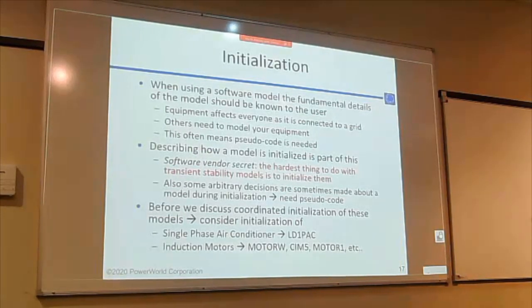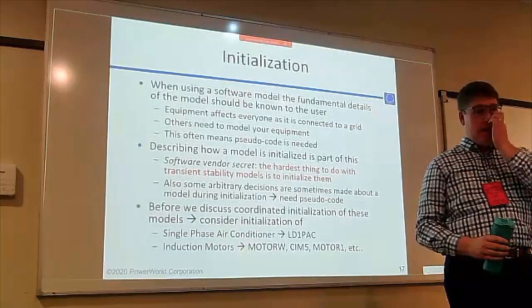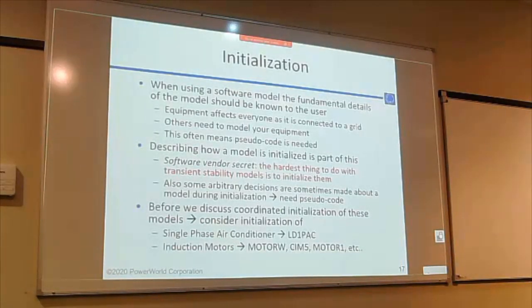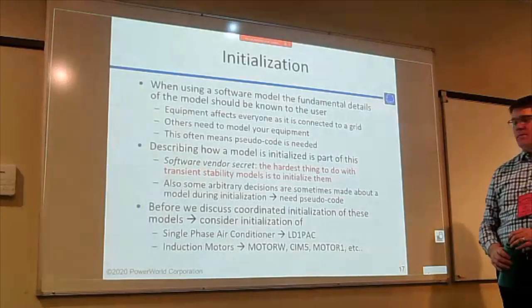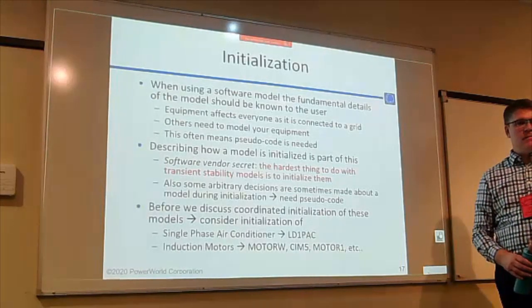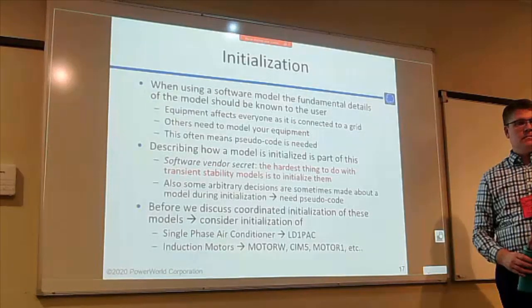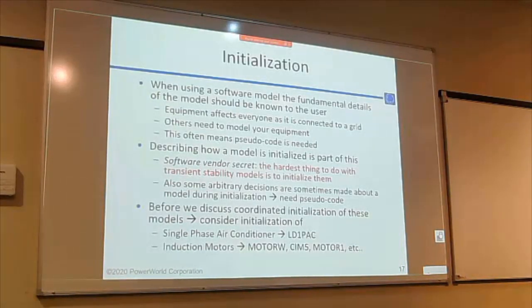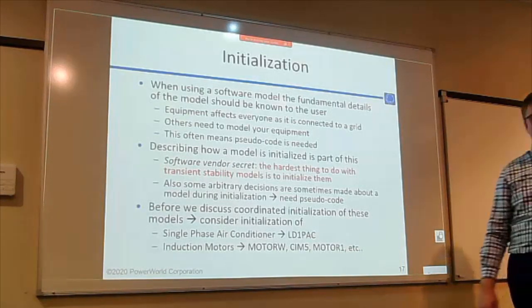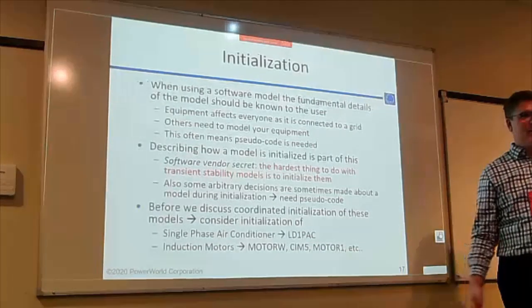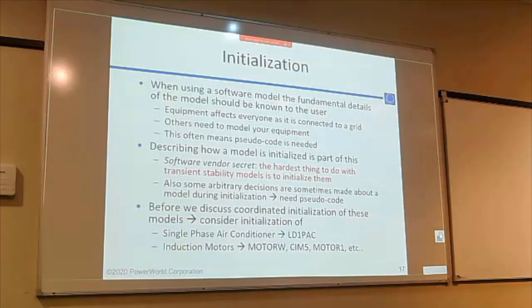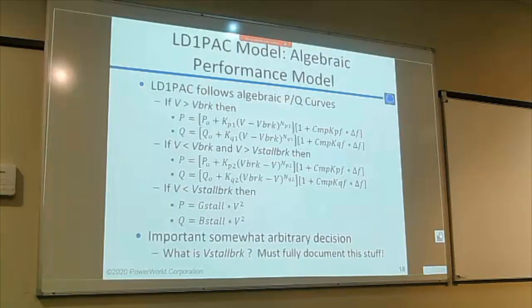So you knew that feature was there. Gordon pestered you because he always wanted to use my paper in the power flow world. So probably 70% of it's now implemented, but for the last 30%, instead of using constant power, you use the zip equivalent models in the paper. Then it's accurate down to about 0.7 per unit, assuming you believe your composite load model and the percentages there, and you have a more accurate power flow steady state simulation. Your power flow steady state isn't accurate below 0.7. Right, exactly, so it's great. All right, a comment about initializing these models.